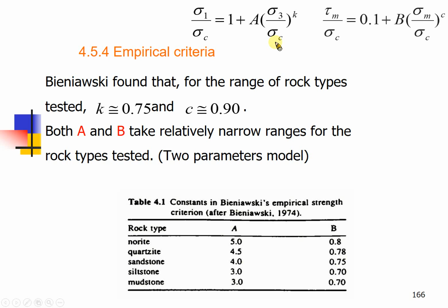Anyway, for rock mechanics, usually we try to use empirical equations to get C and phi, because the triaxial test is not as frequently used as in soil mechanics, since it is a little more expensive than the soil mechanics triaxial test. But we should not only rely on these empirical equations. Sometimes the laboratory test is still essential, especially for large engineering projects. Okay?